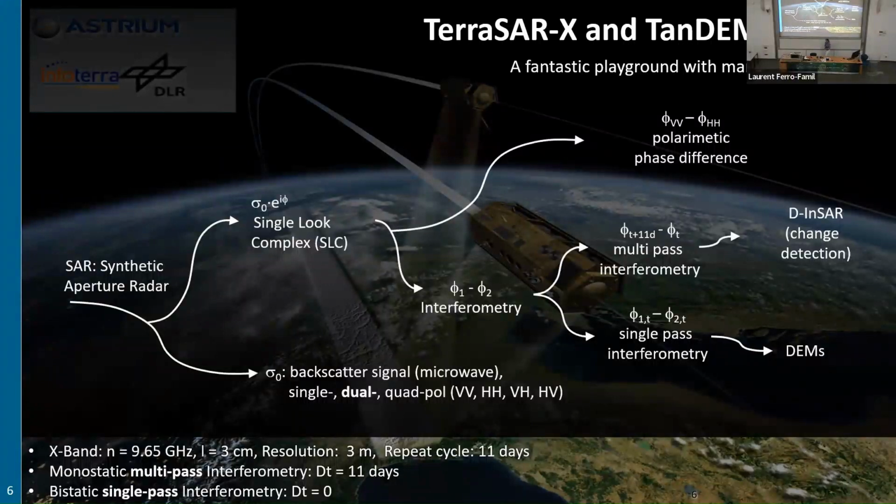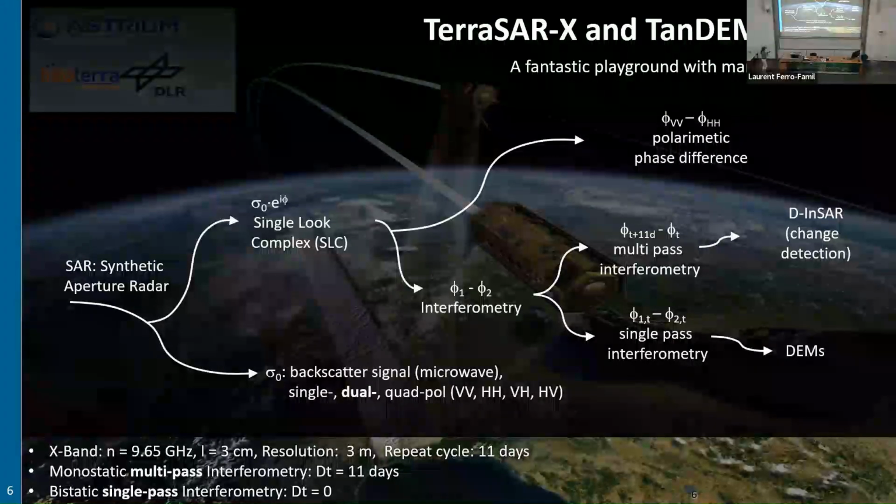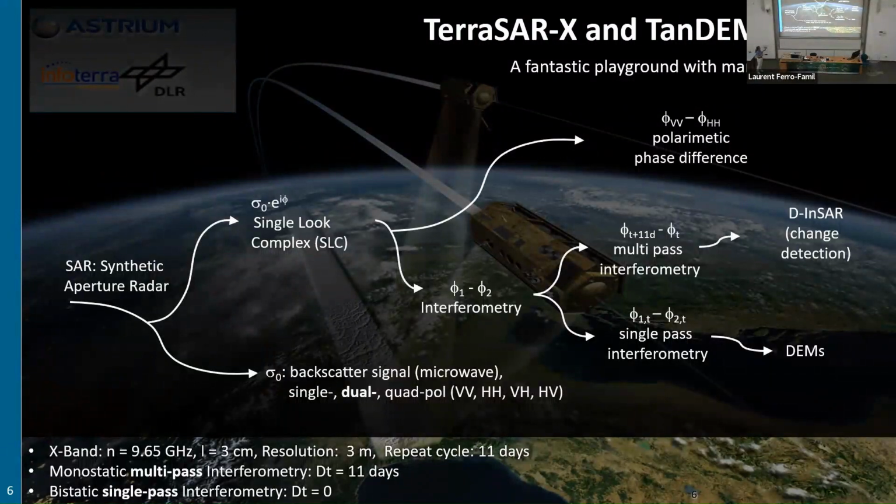So what you can do in addition, for sure, is digital elevation models using single pass interferometry, but you can also go in different other passes. What you get is synthetic aperture radar data, that's clear. In this direction you can get sigma 0, the radar backscattering intensities. This is available in single, dual, and, as said, experimentally also in quad-pole polarization. Today, most of the time we use dual pole. The digital elevation model that has been constructed globally was done in single pole, in HH polarization.